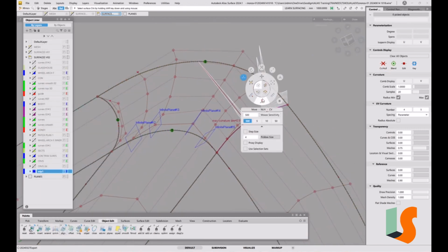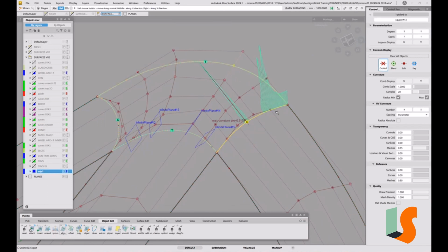Now if I try and move these normal to try and fix that end point, it's very unlikely that that's going to work. That's going to affect tangency there, so it's going to break the tangency probably before I get to the curvature alignment. As you can see, if I pick that point, well, that point actually is independent of this edge because it's controlling curvature on that edge, but not tangency, so we might be able to do that. This very end, I'm not even sure whether we can do that in any case by any means, because of that top edge being only tangent,